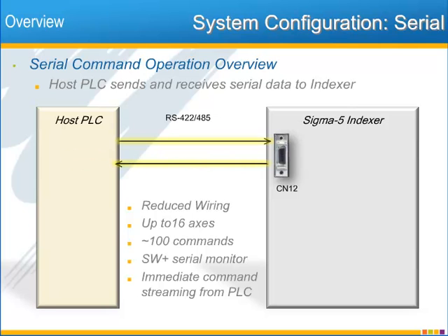It is also possible for the PLC to start a customized move without using the program table at all. And this way you'll have virtually an unlimited number of speeds and distances, which would first be calculated in the PLC and then streamed to the indexer. So as the application requirements change, the moves can change without reconfiguring the indexer's program table.